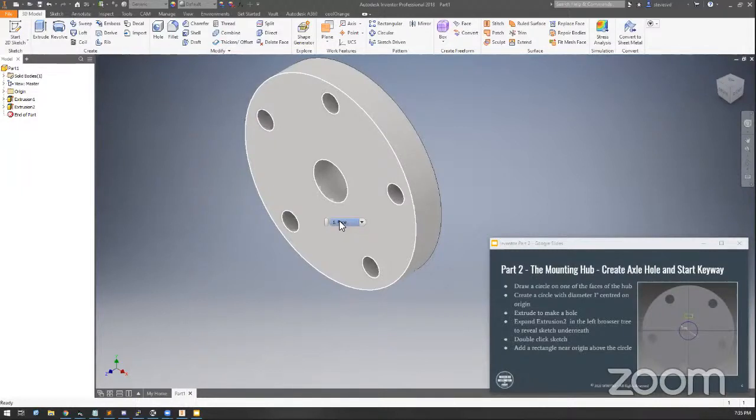And it's specifically designed so that if there is a failure in the system, such that a wheel gets stuck and the axle turns harder, or you have so much torque that things need to deform in order to allow physics to do its thing, the key that joins the two things together fails before the hub or the axle, because chances are the key that we're going to be making is cheaper to replace than the hub or the axle itself.